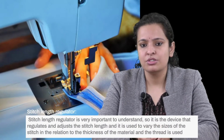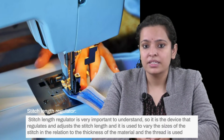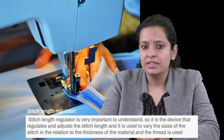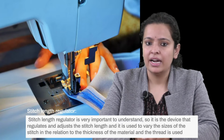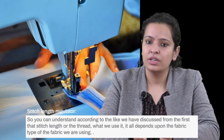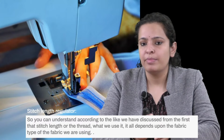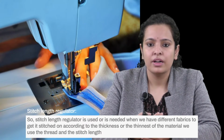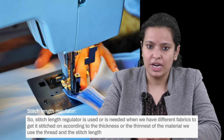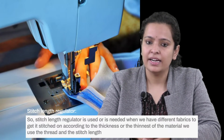Next, on the upright section, we have the stitch length regulator. The stitch length regulator is very important to understand. It is the device that regulates and adjusts the stitch length, and it is used to vary the size of the stitch in relation to the thickness of the material and the thread used. As we have discussed from the first, the stitch length and the thread we use all depend upon the type of fabric we are using. The stitch length regulator is needed when we have different fabrics to stitch, and according to the thickness or thinness of the material, we choose the thread and the stitch length.